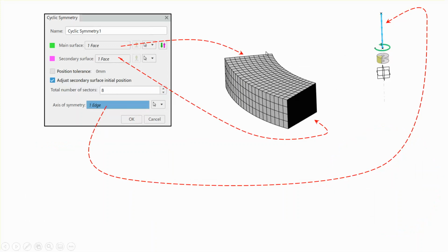you don't have to model the entire disk. All you need to do is to take a particular sector, and in this case, it really doesn't matter because, for example, I can take maybe a 45-degree sector and repeat it 8 times around this thing. But in doing so, you need to select the periodic boundary conditions, the periodic surfaces.